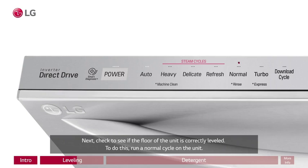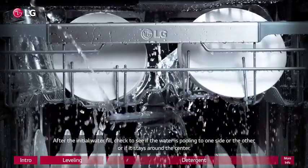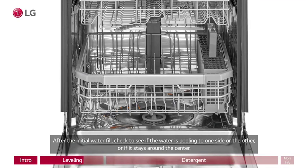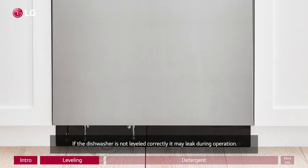To do this, run a normal cycle on the unit. Press the normal touch button on the steam cycles options. After the initial water fill, check to see if the water is pooling to one side or the other, or if it stays around the center. If the water level is off to either side of the tub, then the unit may not be correctly leveled. If the dishwasher is not leveled correctly, it may leak during operation.